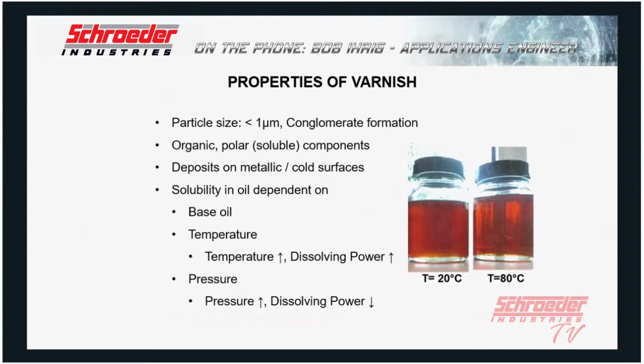They're typically organic. They're polar, so they can dissolve in some cases with hydraulic fluid, as well as dissolve or be attracted onto other polar surfaces within a hydraulic system. That's why you get that lacquer type coating in certain cases in a fluid reservoir, other system components, and so on.